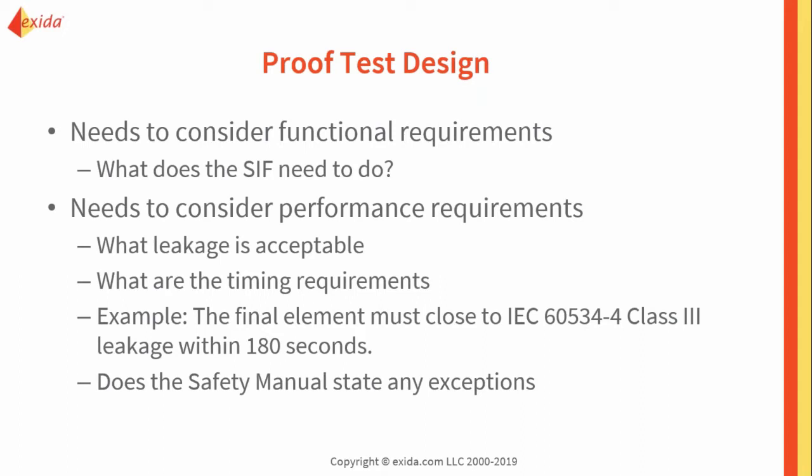Once again, depending on where you are and what you're doing, timing, that process safety time, might be a very critical point in your functional safety management. However, in some cases, it may not. So take a look at what the performance requirements are for your SIF and what's required.